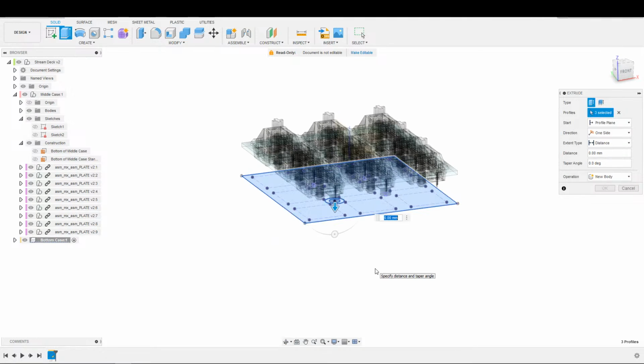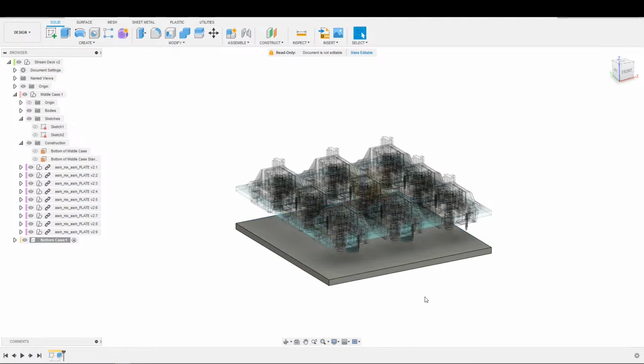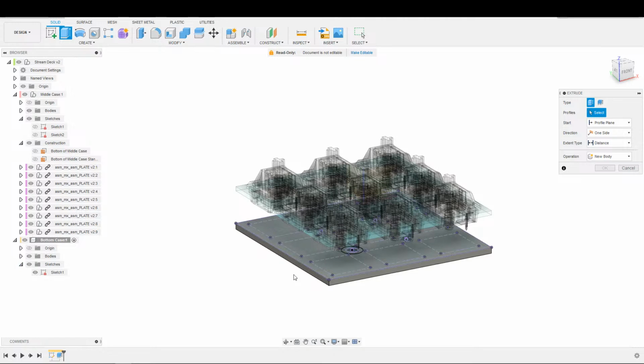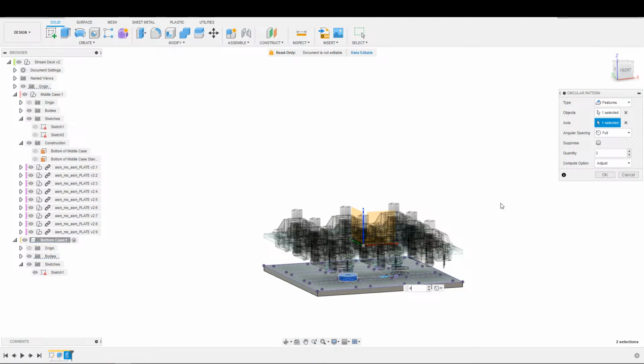We'll extrude everything first, do the base, and then we will come back and I'm going to go relatively thin walls on this guy, because it's not going to be taking very much force. I'm not going to be standing here hammering on the keys of this Stream Deck. It's not a keyboard. I'm just reaching over every once in a while to toggle or switch scenes or whatnot. So it doesn't have to be particularly sturdy, point being. So there's our bottom, and then we can toss this guy up here, and we'll go up again. Just 2 millimeters is fine, because all it's doing is keeping us centered. As before, circular pattern works just fine. That guy around the origin 4 times, and hit OK.